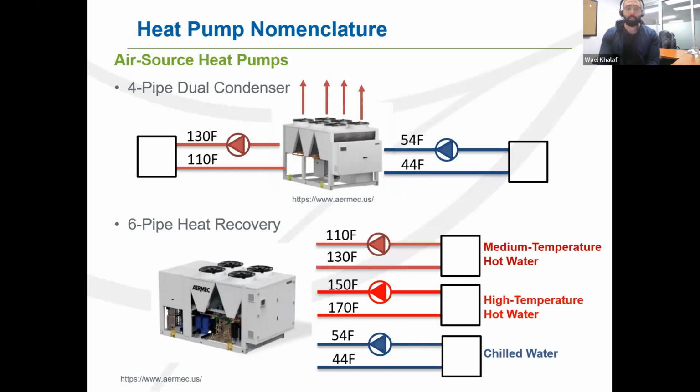So it's great for applications where heat recovery is needed but not available all year round. A great application for this would be a dehumidification load where I need to produce chilled water, but I also have a big reheat load. Every time I produce chilled water, I can take that cooling effect, raise the temperature using my machine, and then reject it to a reheat loop.